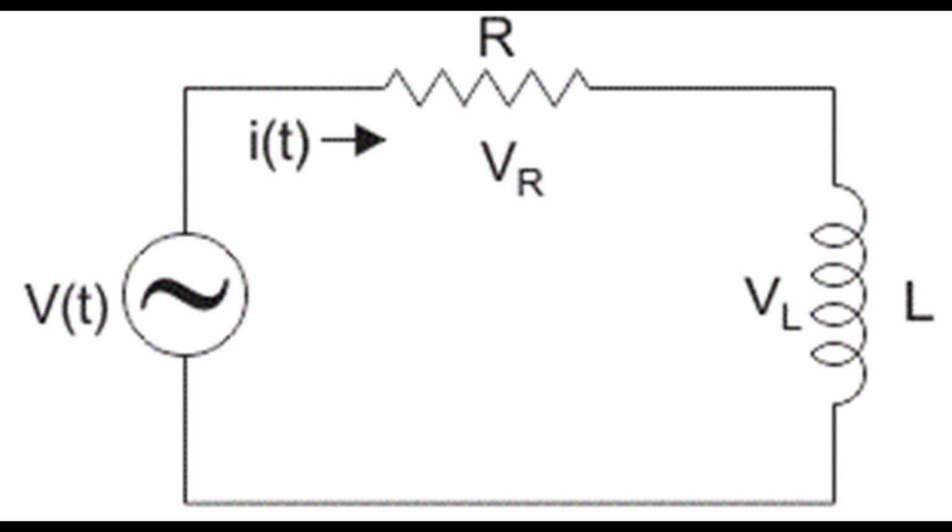In this experiment, I will try to calculate the inductance of an RL circuit with AC voltage using a setup as shown in this figure. I'll connect the circuit elements on a breadboard and measure the voltage across the inductor. The potential difference across the inductor is related to the inductance as in the formula shown.